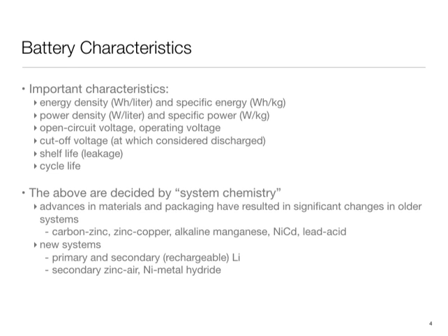What matters to us as system designers is that a battery has certain characteristics: how much energy per unit volume, how much energy per unit mass, how much power it can supply, what its voltage is, how long it will last, and what the leakage rate is, as in I charge the battery and every delta time it is losing some of it. All these are numbers and they depend upon the chemistry of the battery. There are a bunch of other things, like how many times I can recharge them, and all these things play out in the overall picture. Some of them affect the physical form factor, and others affect the way we run these systems.